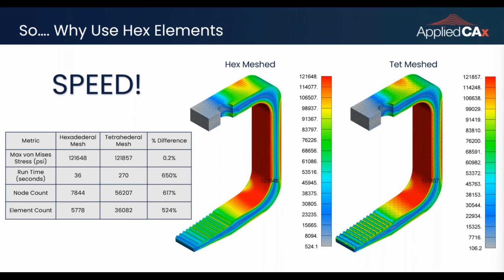So it's not always going to automatically give you full hexahedral elements through the entire structure. It's going to be mostly hexahedral elements. There's going to be certain parts of your geometry that are not hex meshable, so it might use tetrahedrals. And then to transition between the two, it's going to have to use wedges and pyramids. You're also working with a mix of linear and parabolic. As Jeff mentioned earlier, with the tetrahedrals, you have to use parabolic, you have to use mid-side nodes.